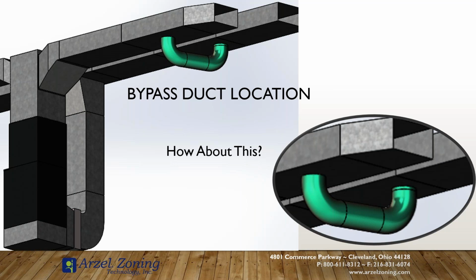Now, it's not always probable to do this when someone uses trunk dampers instead of branch dampers. So if that's the case, you may not have the option of coming off of your trunk line with that bypass duct and you have to come off your plenum. But if you have to do that, then run the pipe down the return air so it's not coming directly into the drop. So take the pipe that you're using as a bypass, get it away from that drop, and don't just dump it directly from plenum into return air drop.